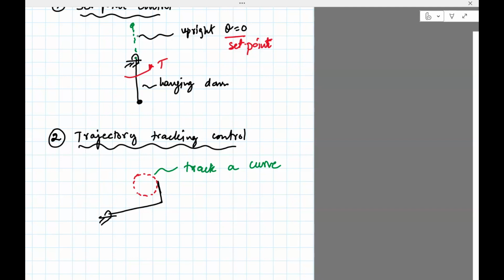So we will actually look at trajectories. Trajectory generation was a precursor to this. For something like a circle, we know the trajectory should be as shown there. But for something like, say, we specify a point A and a point B, we would like to get it to go from point A to point B in a smooth fashion, without any jerk or velocity discontinuity and so on. So that's why we did trajectory generation, which will generate the trajectory for the robot.